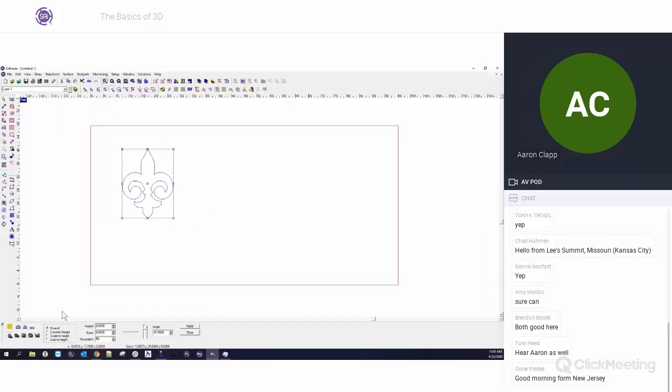I'm going to go over some quick settings here. Typically, what we'll start with is a flat, no thickness relief. You don't always have to start with a flat, no thickness relief, but I like to, because if I don't want any additional height added to my texture later on down the road, I want the thickness to be what I want it to be, then adding a no thickness relief is the best place to start.